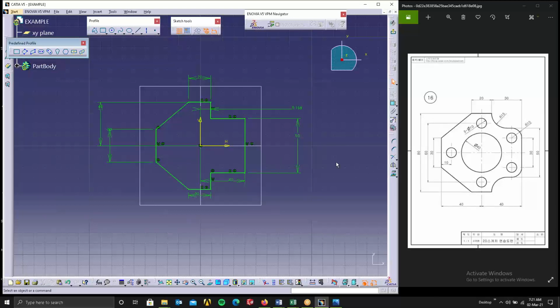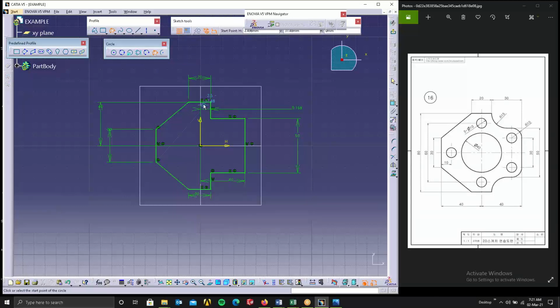Okay. So now we can straight away use the angles. So go to the circle, drop down icon. So over here they have the center point, or else what we can use is we can use this command, 3-point or angle. So you can just select this 1, 2 or 3-point we can use.